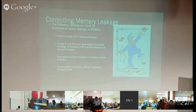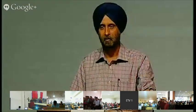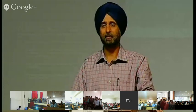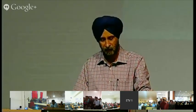Now there are various other techniques to control the leakages. They are employed in any digital circuits also. You have learned that for each transistor there is a concept of a threshold voltage. Normally the threshold voltage of all transistors is the same, but if you have to control leakage, you have to make transistors having different thresholds. That is known as multi-VT.